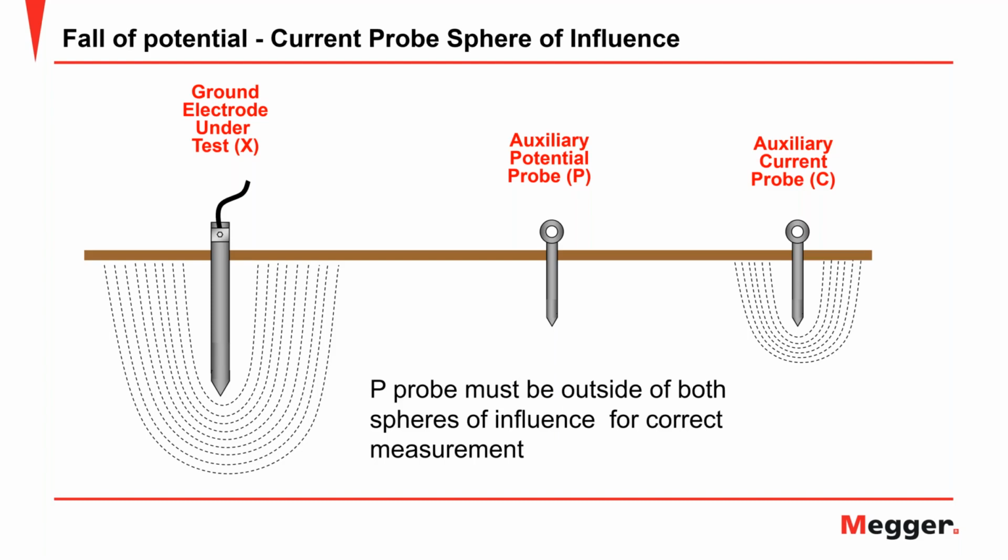That enters into your measurement. It is normally very little and can be disregarded, but if you're trying to measure a very low resistance ground, like a substation under an ohm, then sometimes it's a little more convenient to do the extra work if you have a 4-terminal tester and run all 4 terminals, 2 of them to your test ground, and then of course your current and your potential probe. It makes the measurement just a little bit more precise, which can be helpful in a very low ground measurement.